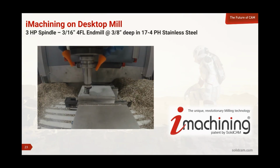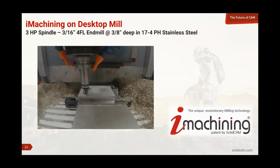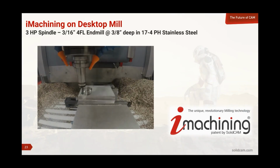Now, the reason we can do that is because with each movement of this morphing spiral that you're seeing here, as the cutting angle is ranging between minimum and maximum, we are also modulating the feed rate so that the chip thickness at the actual cutting angle remains constant. Therefore, the force load on the tool, on the material, and on the machine also remains absolutely constant. It's a very, very powerful way of doing cutting.